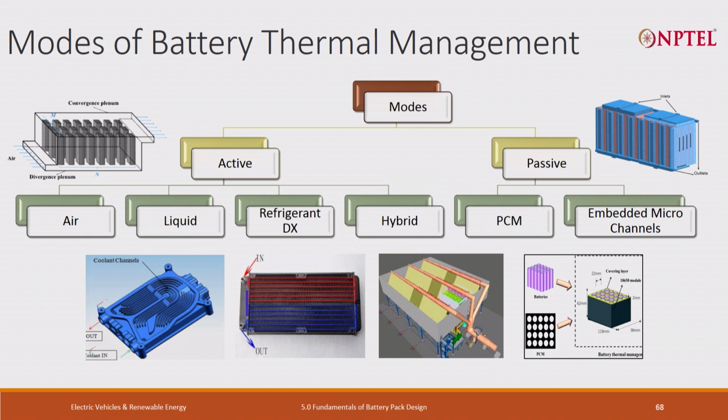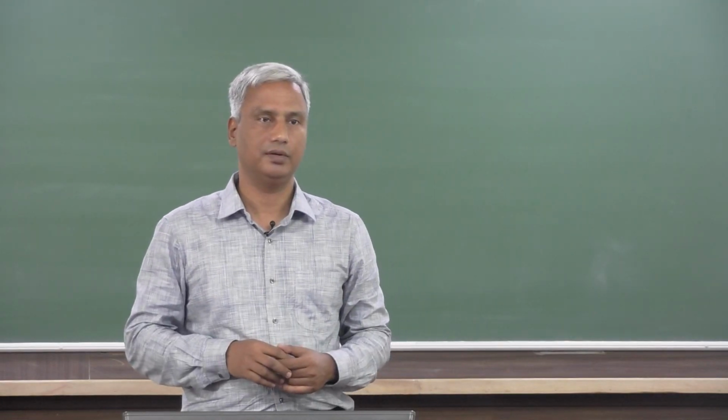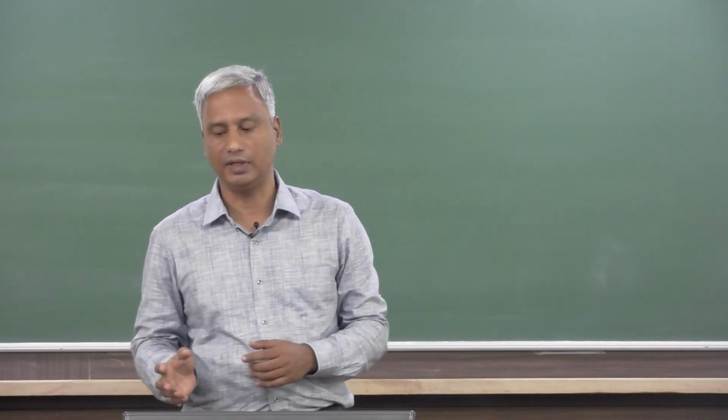The second is, if we combine it with heat pipes or thermosiphons or such things, that helps by phase change, again by phase change, but at much lower cost, by capillary action or thermosiphon action, to manage the heat properly. So it takes heat from the battery pack and releases it into the ambient in a much more efficient way.